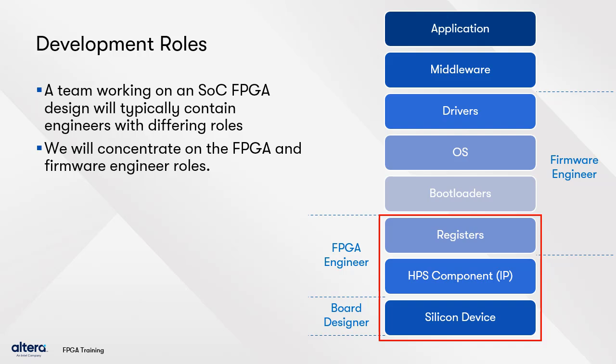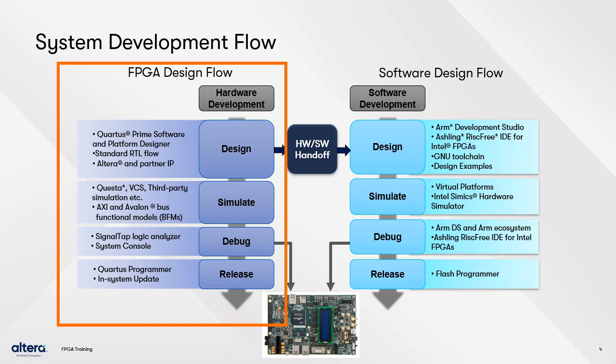Crossing into the software domain, we may see the bootloader development and driver development for a particular IP component. Above that, there's an operating system, middleware such as Ethernet stacks, and the user application software sits at the very top of the development layers. For this presentation, which is meant for FPGA engineers, we'll focus on the bottom three layers: the devices in which IPs are implemented, the IPs themselves, including soft IP in the FPGA, and the register view to allow the lowest level of software access.